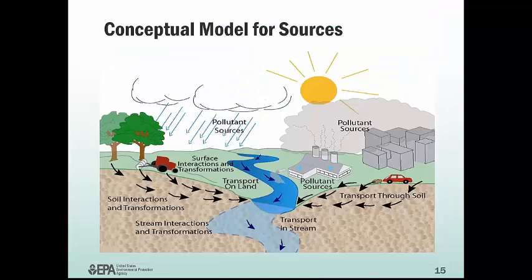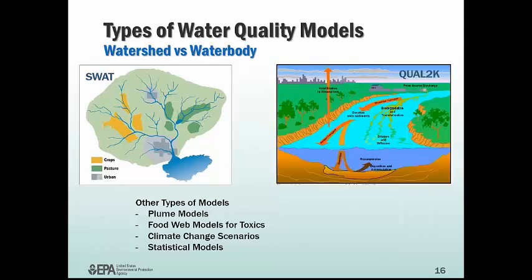What are the potential sources of pollution that might be modeled? Let's say you're looking at mercury getting into this stream shown in this schematic. Is atmospheric deposition of mercury a significant contributor to this particular area? Are there point source discharges from industrial facilities nearby? Or is stormwater likely a culprit in the loading of mercury to this particular water body? And so all of the answers to those earlier questions should help determine the type of model or models that you would want to focus on.